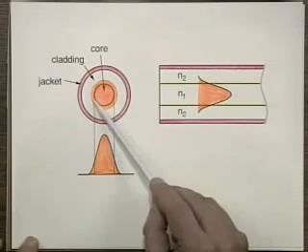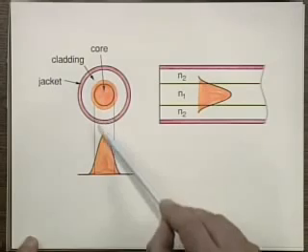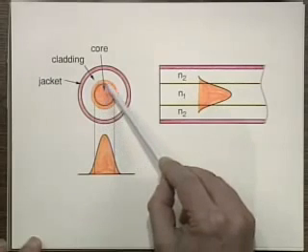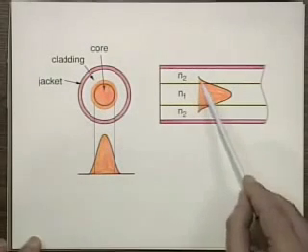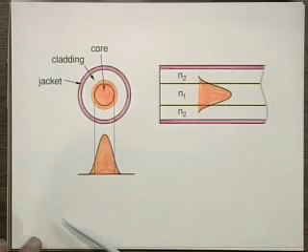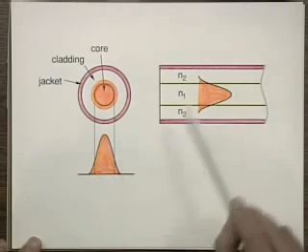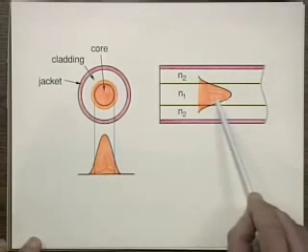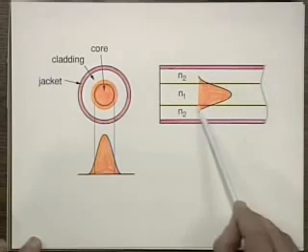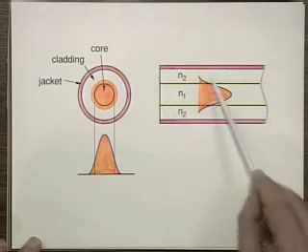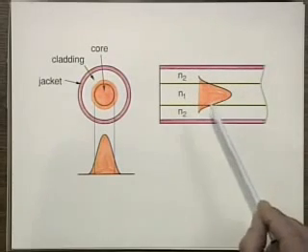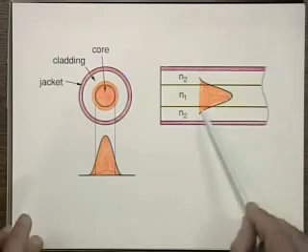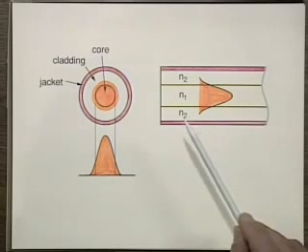So you can see this is the size of the core, but this orange, if you can see it as orange, basically extends beyond the size of the core, and that's what we call single mode propagation. Here is the field distribution, here is the size of the mode. So it extends a little bit into the cladding. Most of it goes into the core, part of it goes into the cladding, and propagates right down the fiber. This ray idea is fine for explanation, but when you do the proper calculation, that's what you get. You get this for the lowest order mode.